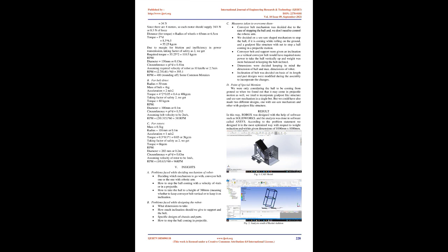Equals 55.25 kg/cm. Due to margin for friction and inefficiency in power transmission, taking a factor of safety as 2, we get required torque equals 55.25*2 equals 110.5 kg/cm.